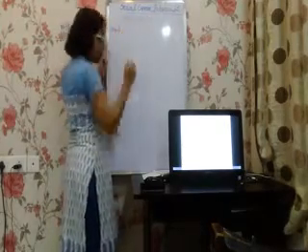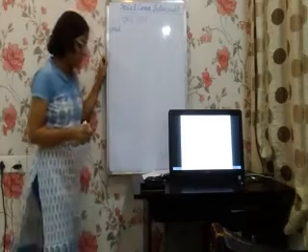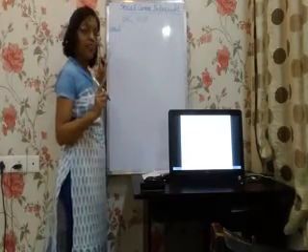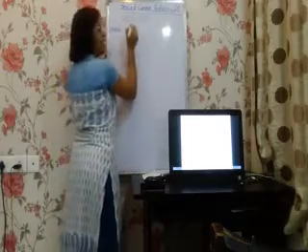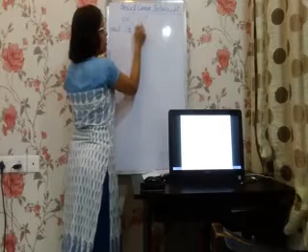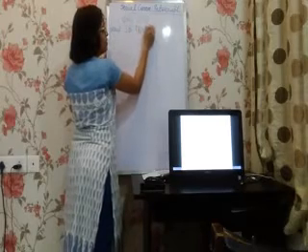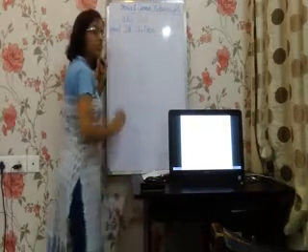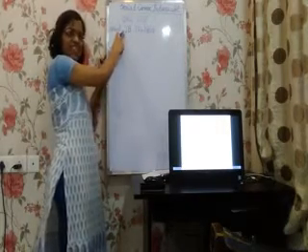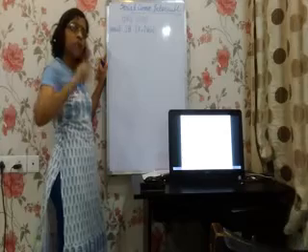Now what I am supposed to do in the serial program? I am supposed to check the transmit interrupt flag as well as the receive flag. So what I do, I give any one of them. JB, jump if bit, transmit interrupt flag, suppose next. If TI flag is raised, means 8051 is working as a transmitter.